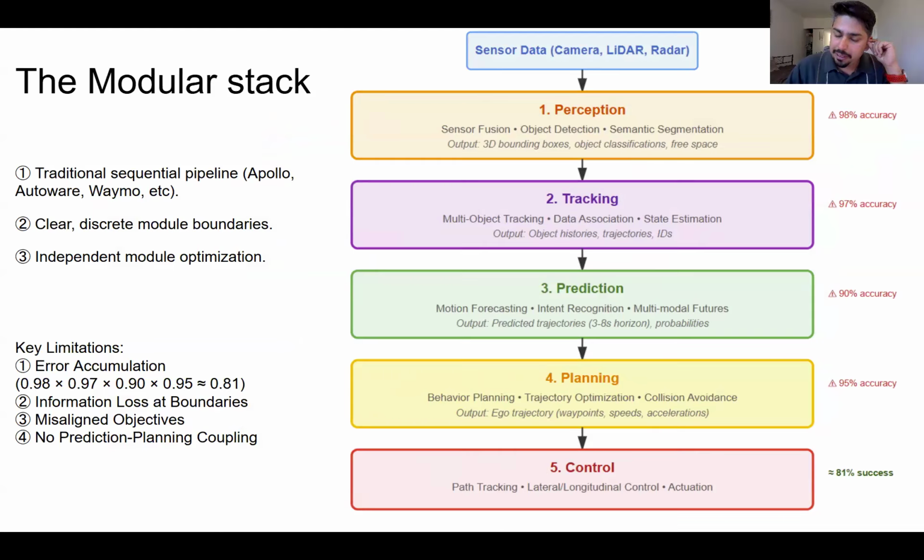For the planning, there is a time parameterization of the other agents in the prediction. So each of the predictions is not just a spatial prediction, it's a spatio-temporal prediction. So you have a time profile in the prediction module, and the planning itself is also generating these trajectories, which have waypoints that are not just spatial, they are spatio-temporal.